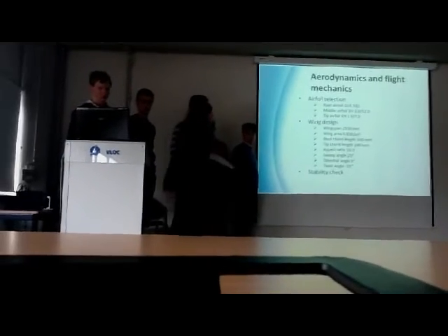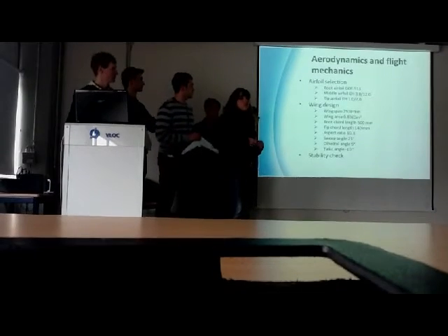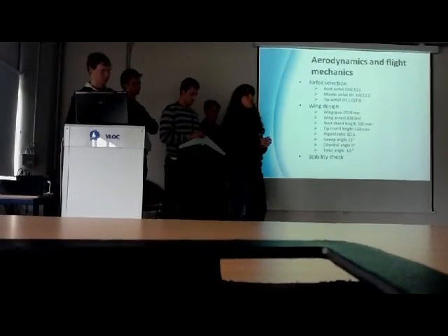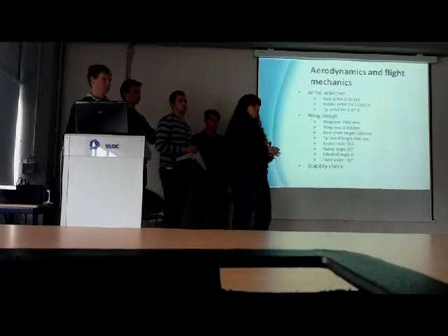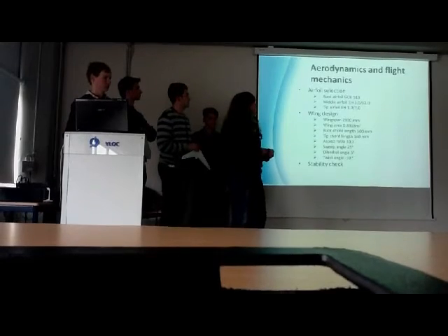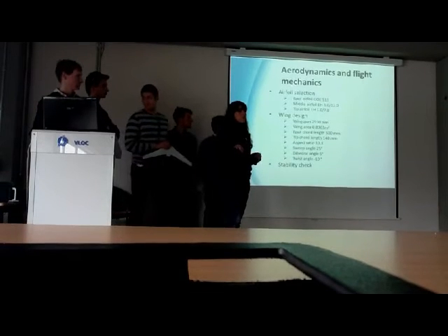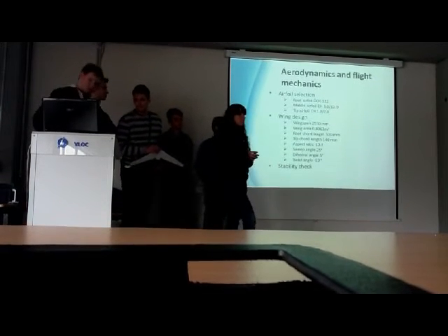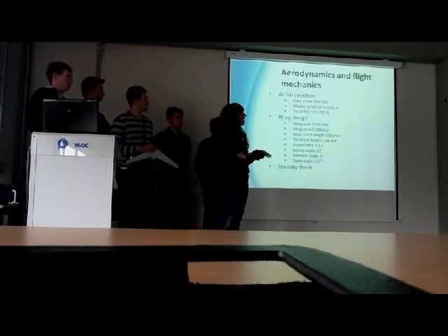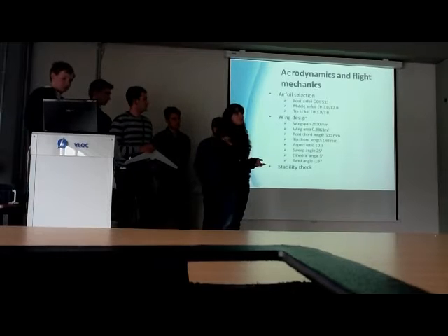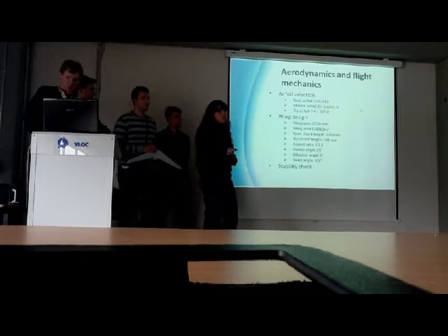So we had 3 different airfoils, because in the root of the plane we need a more extremely thick airfoil so that all the equipment can fit inside. So there's the GOE 500. And at the tips we don't need that. We need a thinner airfoil, so we choose another one. But we couldn't make the transition from the root to this thin airfoil just like that, so we also have in the middle a third airfoil.